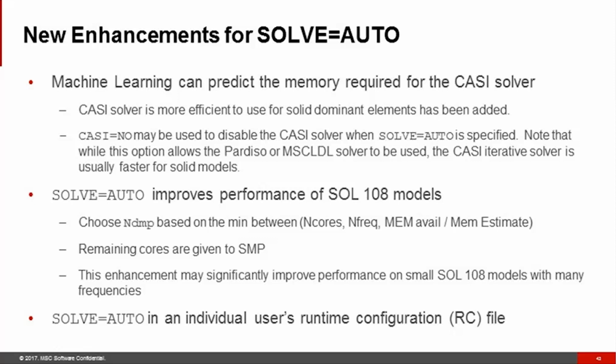The solver will examine your model based on the element type, solution size, and memory requirements, and select the most efficient option to run the analysis based on the solution and other options. The combined option SOLVER=AUTO selects the best solver for your 101 models, 103 models, 111, and other solutions.